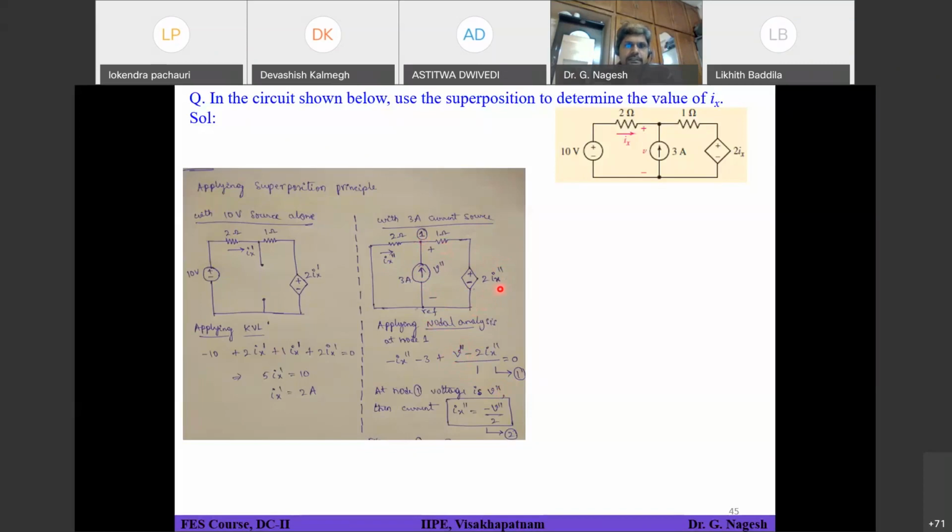It is a dependent voltage source, since plus and minus signs are given. So some voltage minus another voltage divided by resistance gives me the current. So all three terms in your equation are currents. Is the third term clear to everyone, or does someone have any confusion?